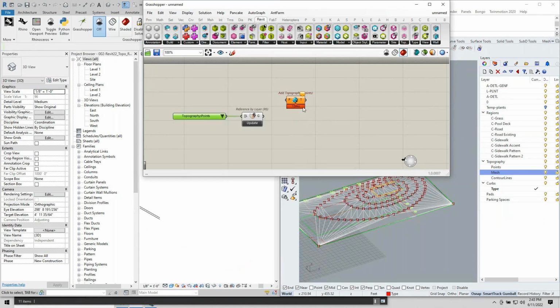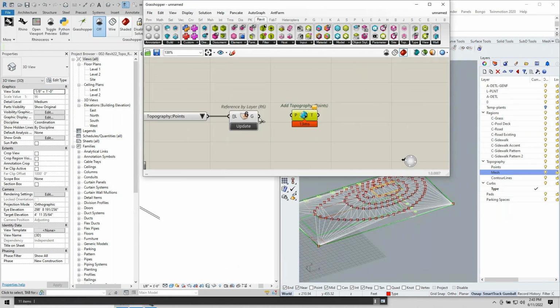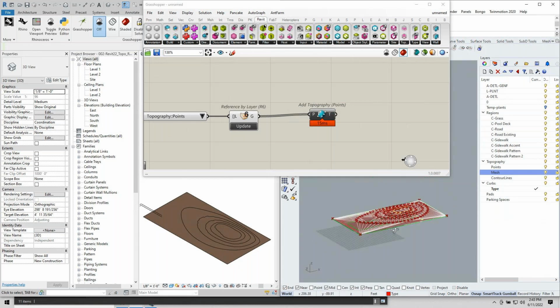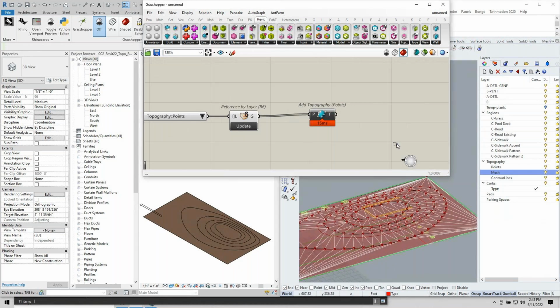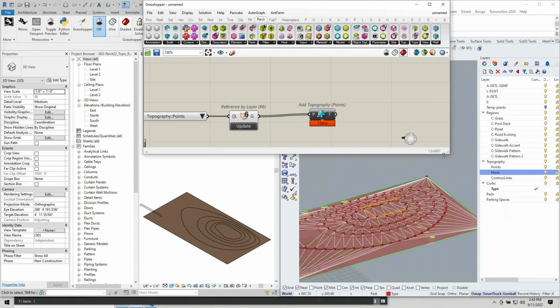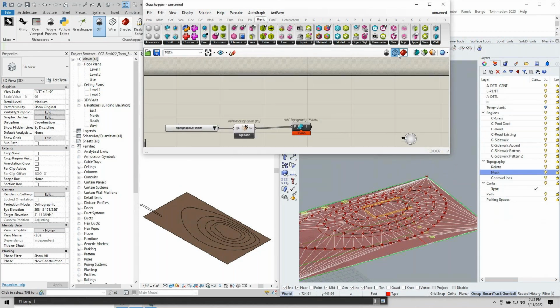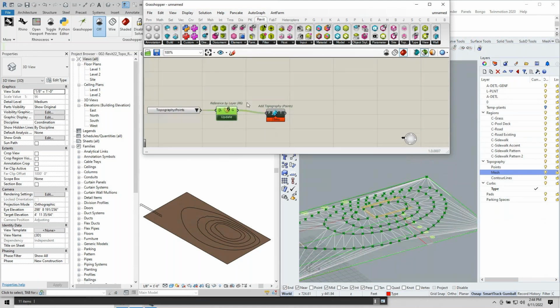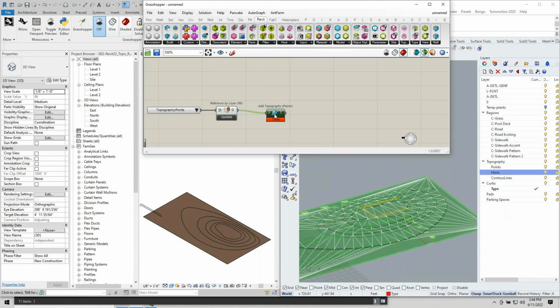Now we're going to go ahead and add our topography by points. This is a lot more flexible. I don't know how familiar you are with Grasshopper, but we don't need the previews. So don't draw any preview, wireframe, or just selected items, which is really nice if I want to see in a large definition what a particular component is referencing or doing.